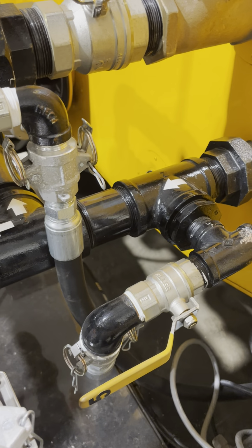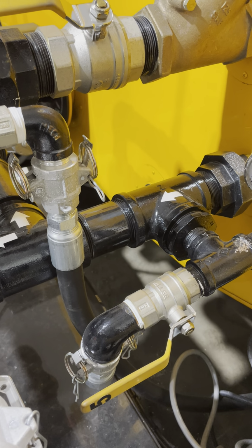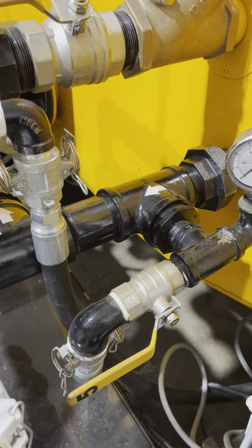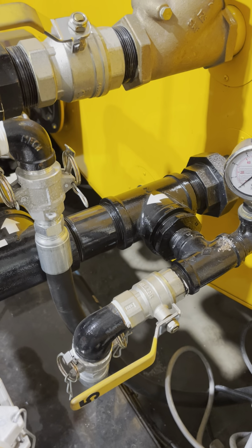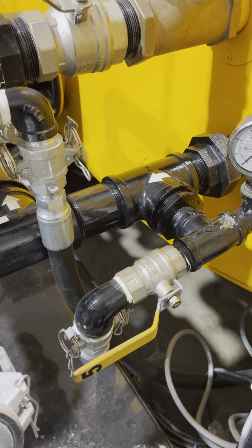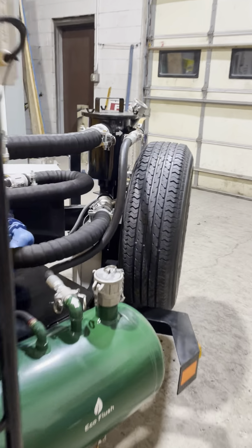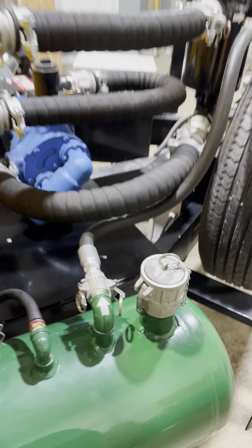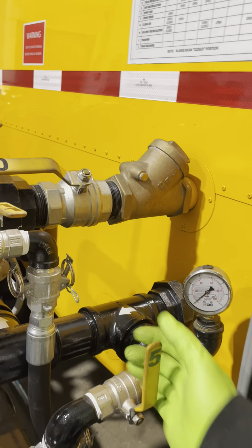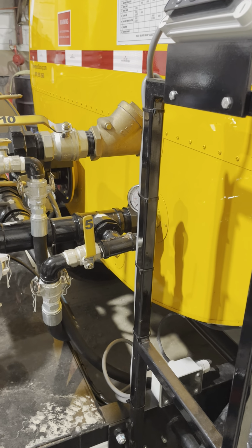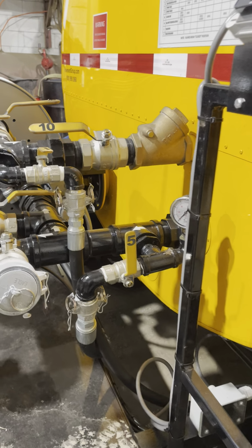Open 5, that's going to allow that solvent to go to the hose wand, but you have to spray it somewhere until it comes out as solvent and not material. Granted, we pumped air through there, but there's still residual material in the line. We recommend a 5-gallon bucket, or taking your hose wand, pop your cam lock open here, stick the wand right down in there until it sprays solvent out. Then you can close off your valve for your sealing wand, which is now full of solvent and soaking. It's going to soak overnight.